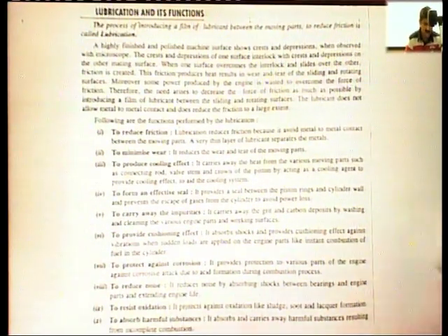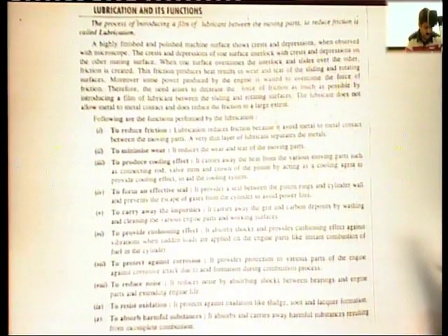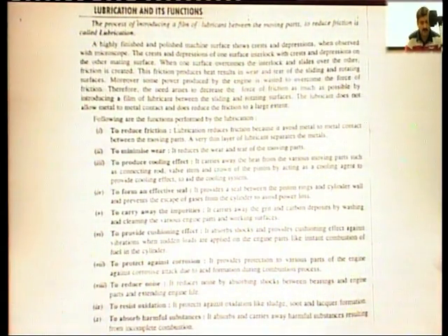To resist the oxidation, it protects against the formation of sludge, soot, lacquer formation, as it covers the moving parts. And next is to absorb the harmful substances like unburnt carbon particles, hydrocarbons during the expansion stroke. It dissolves all these particles and brings them to the sump.